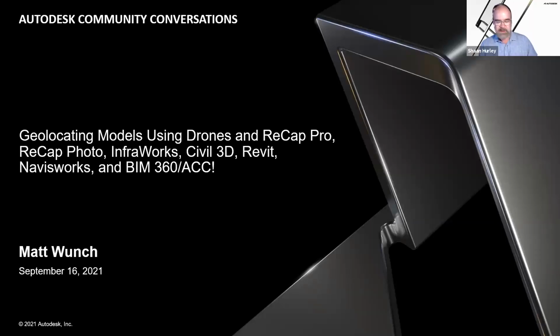There we go. So it kind of zooms us out to the extent of that entire InfraWorks model, that area there. It's chugging through. I'm going to turn off the map for a second because I want to show you something that's pretty cool. Because I have some component roads in InfraWorks, it automatically recognizes those as assemblies. So it brings them over as assemblies, as corridors in Civil 3D. So you don't have to mess around with recreating the wheel on any of this stuff.